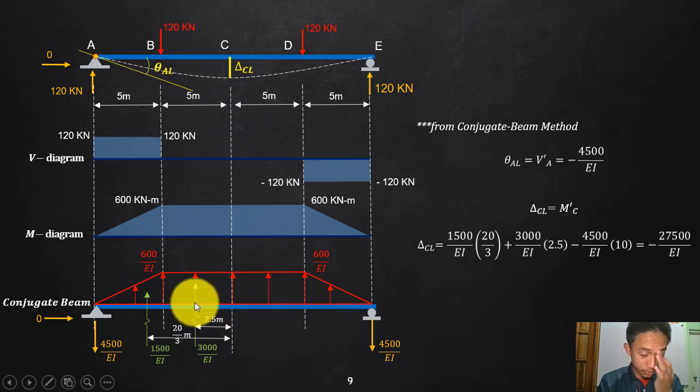So what are the loads in my left side, since I am considering the left side of the diagram? These are the loads, the 4,500, which is rotating counterclockwise, so that is negative. This trapezoid here, I need to break down, since I do not know the centroid of the entire trapezoid, so I will break that down into a triangle and a rectangle, since those have the basic centroids, okay? So what will be the resultant here?